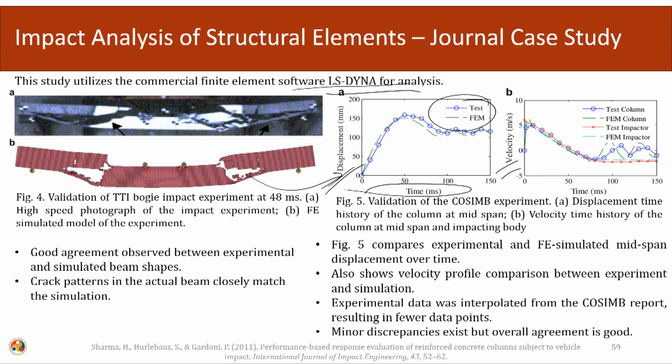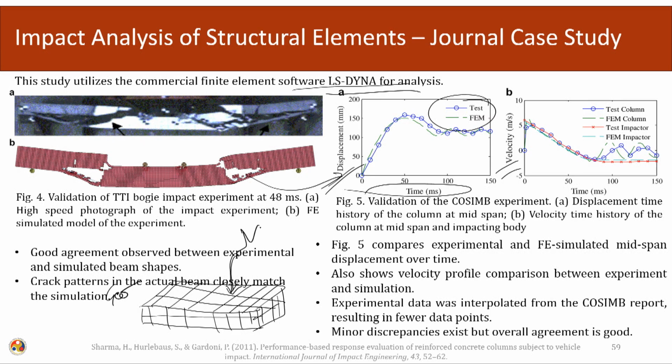For using any finite element simulation, we need to first make the geometry of the system. After we have made the geometry, we need to discretize the system. LS-DYNA is a commercially available software that we can easily use. So, first we will make the geometry of the system, then we will discretize it. After the discretization, we will give the values of the material and the values of the element formulation.